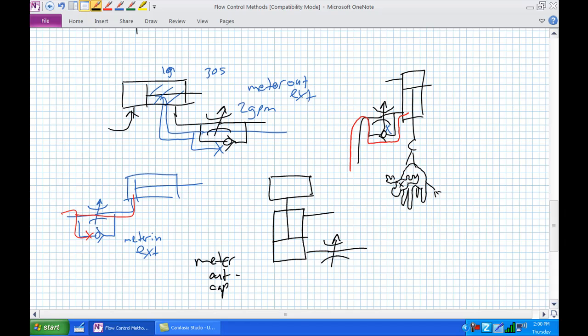Obviously, flow control valve, make it variable. Make it so the check valve forces the outgoing flow through the flow control valve. Means you have to hook it up in that fashion. So again, I want to slowly descend this weight, outgoing flow from the cap end. Can't go through the check valve, it's forced to go through the flow control valve.